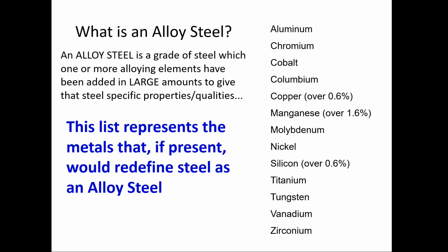We can get a really good, tough surface and still keep the back end of it, the trunk of the knife, a little bit annealed to keep it soft enough that we have impact resistance. So we can hit something hard with this knife and maintain the edge, but not shatter. All these materials here are all very special. This is what's referred to as alloy steel. If they have one or more of these elements, in respective amounts, they're referred to as an alloy steel.